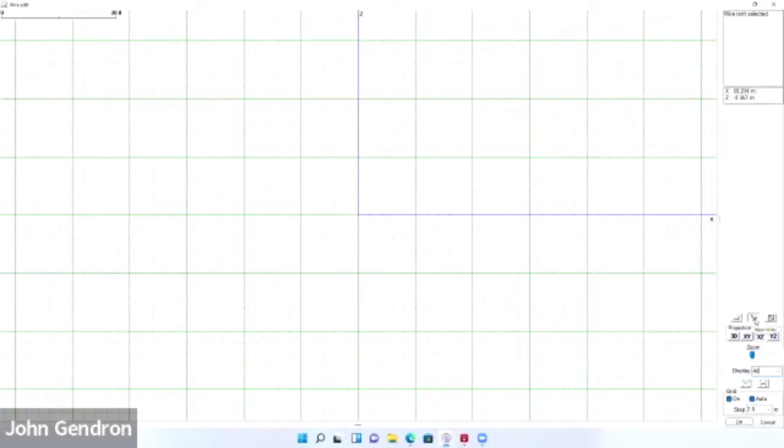It's right above projection where I said 3D XY, you've got the little one in the center that looks like a pencil. Okay. So I'm just going to start a dot here at Z0 and X0, and I'm going to pull a line up, okay? And I can look on the side in that top right-hand corner. You can see where my X is at, 0.357. And my Z is going up and I'm getting close to 10 meters. So I'm going to get this thing to about 10.5 meters, okay? And it's going to snap there.